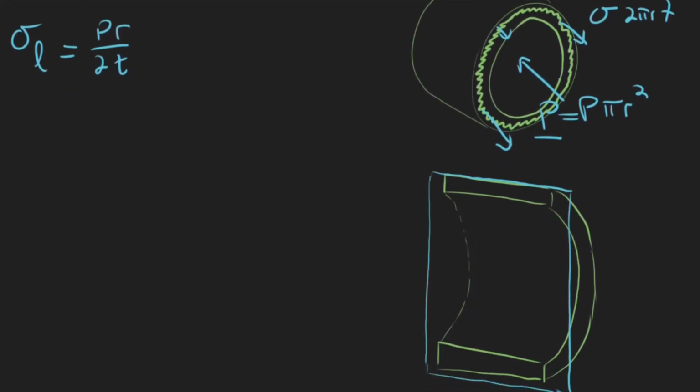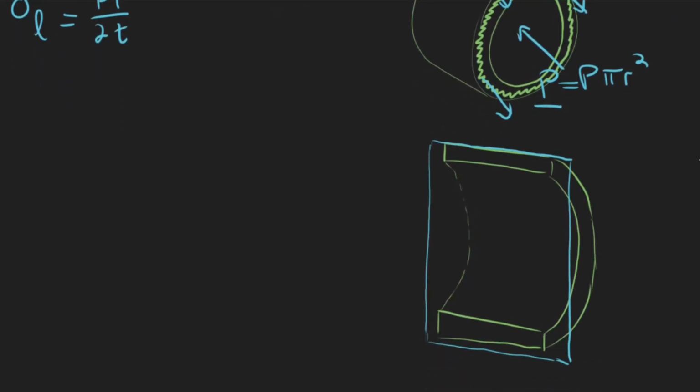But we also have this stress, which is called the hoop stress, which is basically wanting to break it apart in this direction right here. So for this, we're going to have, again, our pressure coming in like this. We're going to assume that it's normal distributed across this square, which is an approximation, but the error is low enough that we can use it in an actual design if you're going to use a factor of safety or something. So we're going to call this our load.